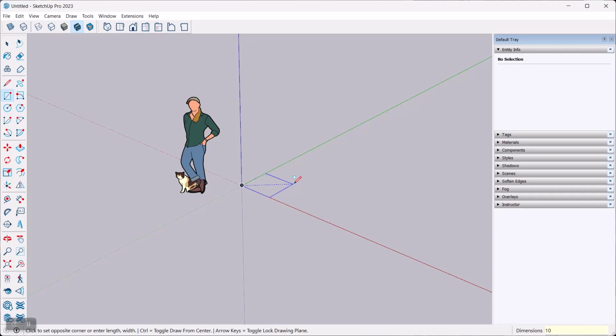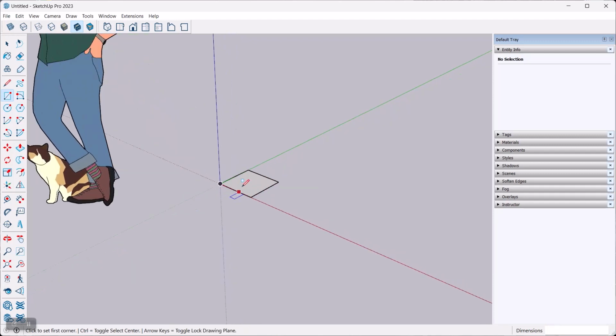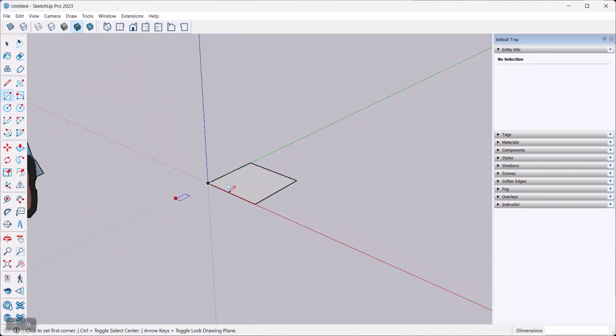And you can enter dimensions, as you see here, with unit symbols, so as in 10 inches, 10 inches. Oopsie, did not work well. Right there. Or you can simply do 10, 10, because for SketchUp, the default unit is inches, and then you can hit enter, and you've drawn something precisely 10 inches by 10 inches. You can always double check things with the tape measure tool right here. And it's 10 by 10. Good, perfect.